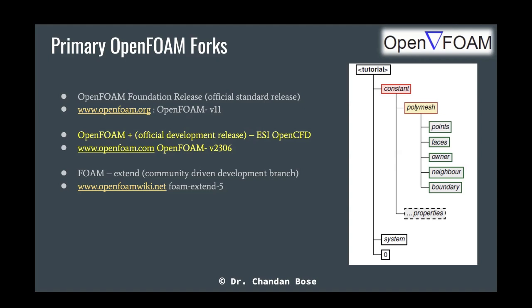So this constant folder will have, first, the information related to the mesh, and that mesh information will be located in the folder called polyMesh. And we will have another file. We can have multiple files, but another mandatory file is transportProperties, which involves the transport properties, which is very intuitive or self-explanatory, such as what the kinematic viscosity of the problem is, right?